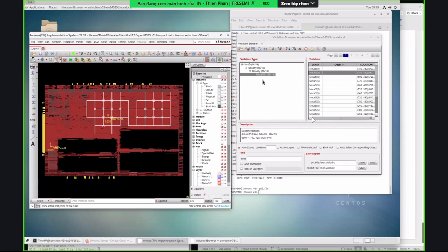Right. Thanks, Matt. Another thing is when we run, let's say STA and extraction, before metal fill and after metal fill, the timing can be different as well. So for the final timing, we want to do all the extraction after, right? Essentially everything has to be in the design, and then we extract the parasitics, and then we run timing, right? So that's why at the end, you're so close, but you're not done, right?